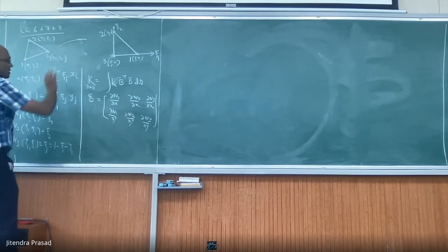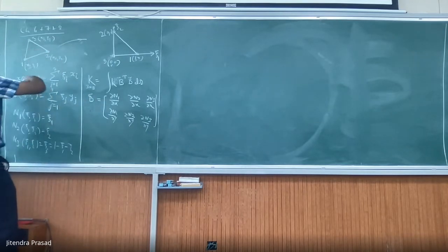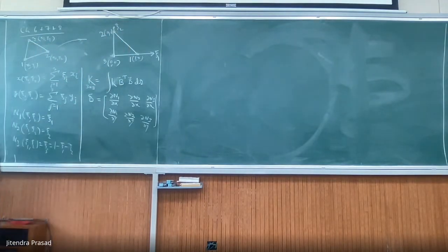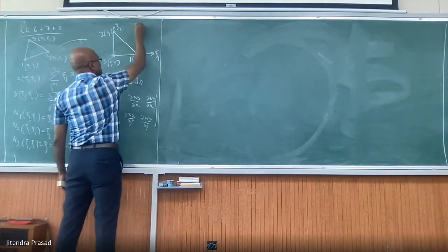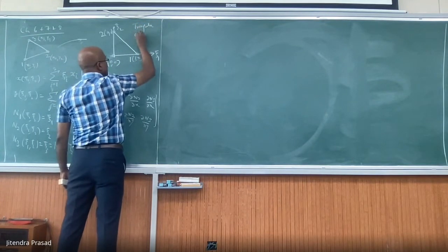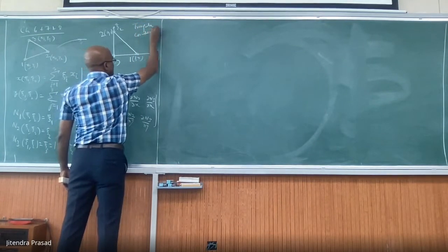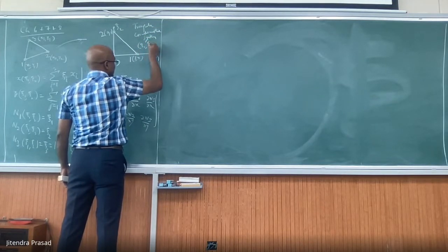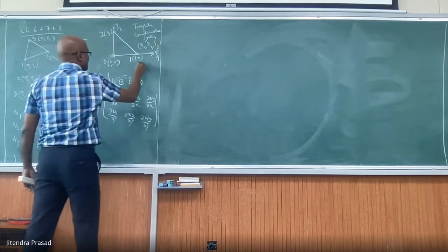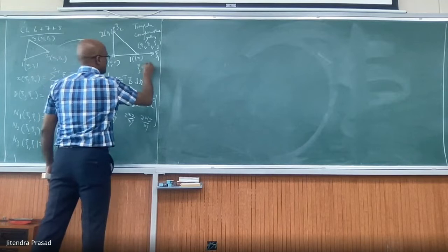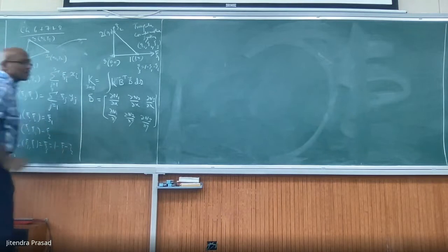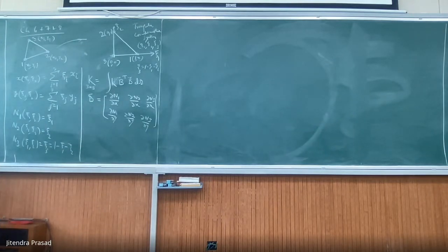So this is isoparametric. We are making an isoparametric triangular element, using the triangular coordinate system. We understood that because we have the xi1, xi2, and xi3 concepts, where xi3 is nothing but 1 minus xi1 minus xi2. We have to find this, and we will use the same method as we did earlier.